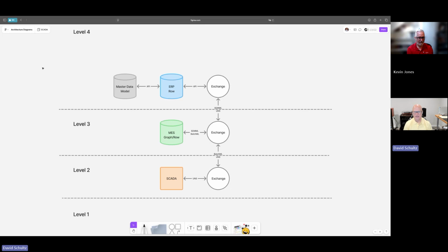So again, we're going to have this exchange mechanism between your level 3 and your level 2 systems. And this is where we get into the SCADA, that's your supervisory control and data acquisition. Now we're into this visualization piece where we're going to be historizing data. And as the name would suggest, it's the overall supervisory control. I think people are fairly familiar with what SCADA does, but it's generally the pictures that are on your screen. It's the operators, it could be a level, or it could be an HMI that sits there, but this is that level 1, level 2 domain. It's the actual human machine interface for people to look at what's happening. It's the visualization layer, if you will, of the actual manufacturing process.